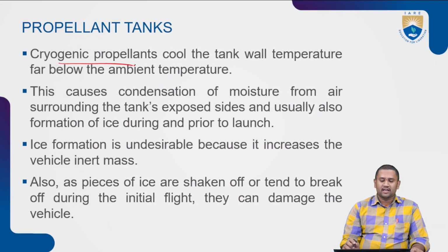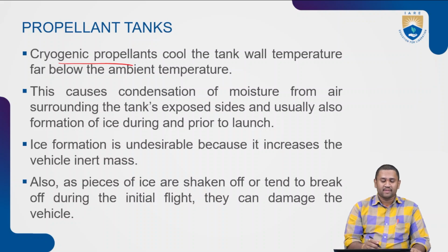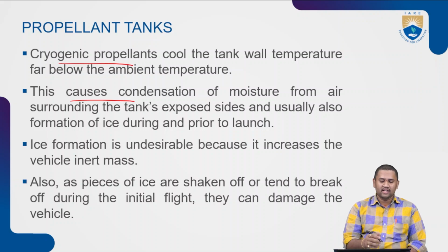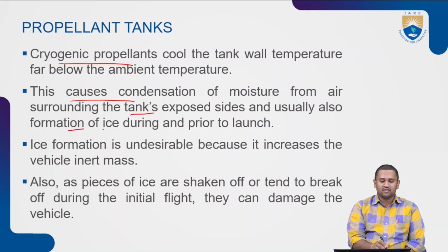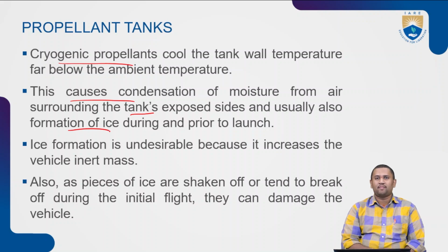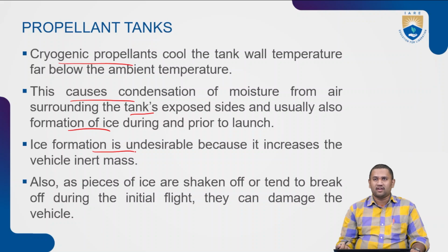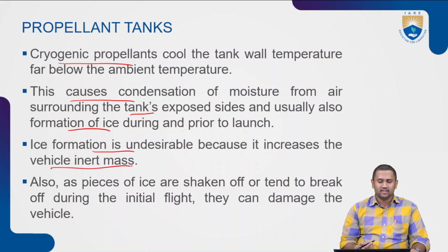The cryogenic propellant cools the tank wall temperature far below the ambient temperature, and this causes condensation of the moisture of the air surrounding the tank's exposed sides, and usually also the formation of ice prior to launch. The ice formation is undesirable because it increases the vehicular inert mass, or the launch mass.